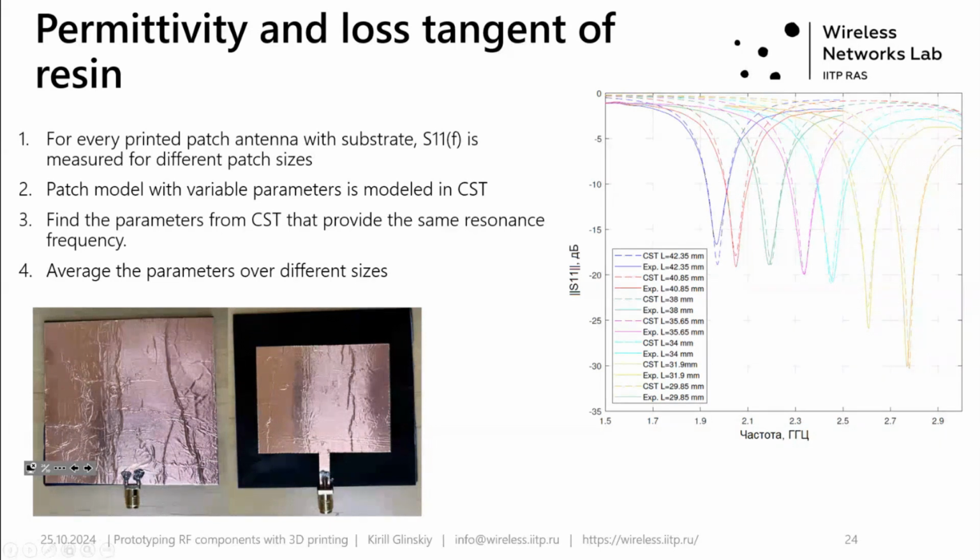We then measure its resonant characteristics, but not just for one size of patch antenna. By cutting some part of it, we can obtain second, third, and other iterations of this antenna with different patch sizes but the same substrate material. For example, here we have up to 6, I believe, measurements for which we obtained the resonant characteristics and measured their return loss at the resonant peak.